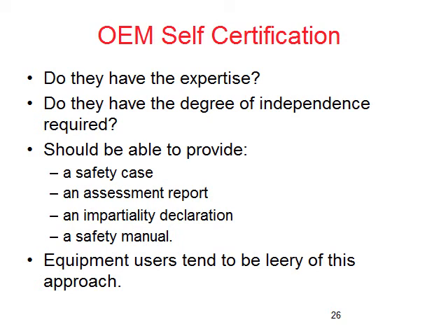That's a pretty high hurdle to cover. Second thing is there has to be a degree of independence. So if it's SIL 1, it has to be done by an independent person. If it's SIL 2, it has to be done by an independent department. And if it's SIL 3, it has to be done by an independent organization. So even if we just looked at SIL 2, you have to have an independent department from probably the design team, the engineering department, in ways of management and resources such as funding to do that.